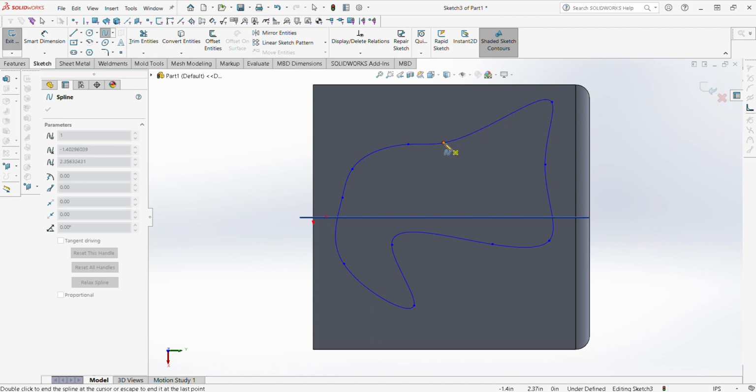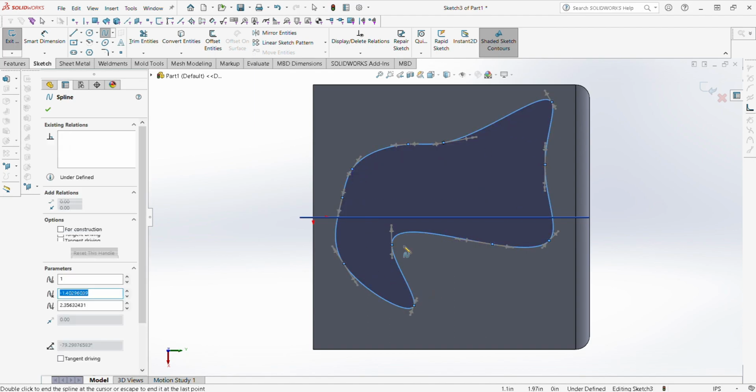And then you have to reattach. I mean, you don't have to reattach it, but if you want to do something with it, you have to have a closed surface. So if I did something that was open, you wouldn't be able to cut or extrude this as a feature. And that goes with anything. If it doesn't have a profile, then it won't allow you to do anything.